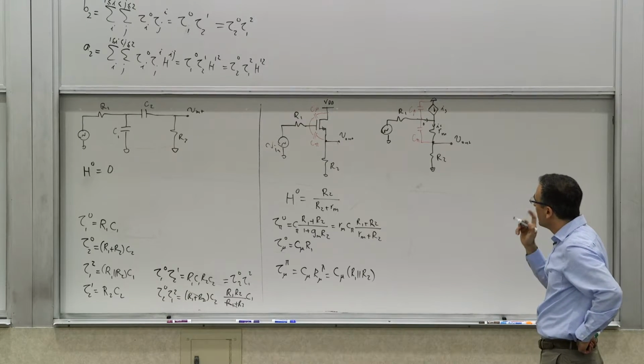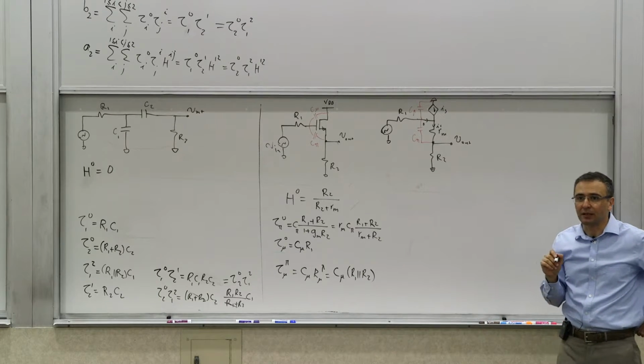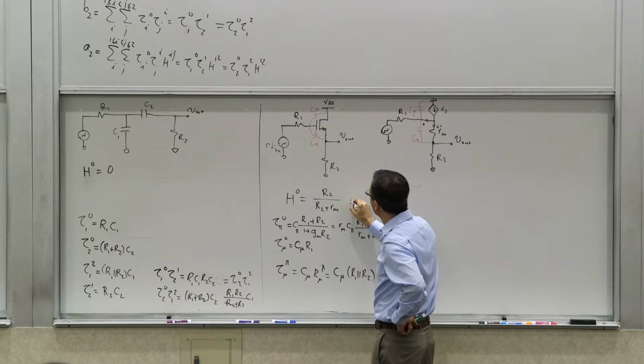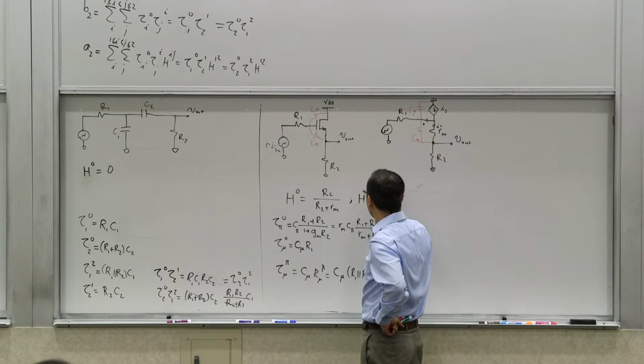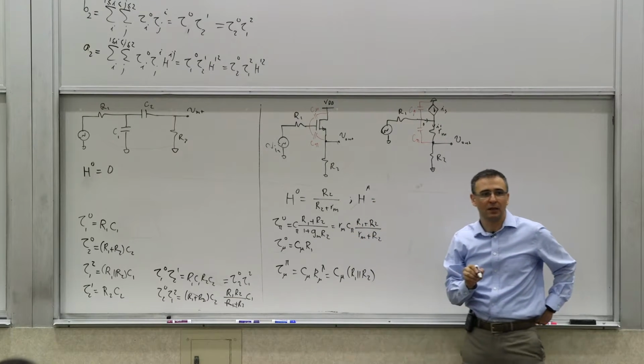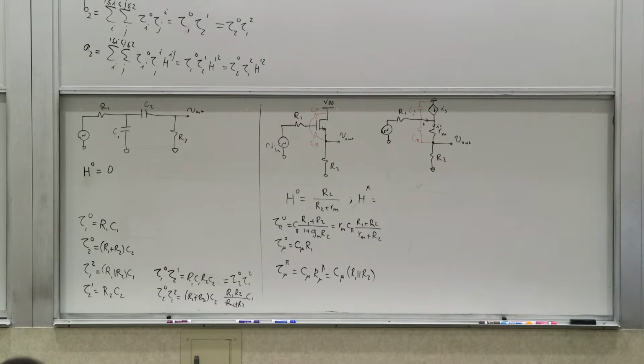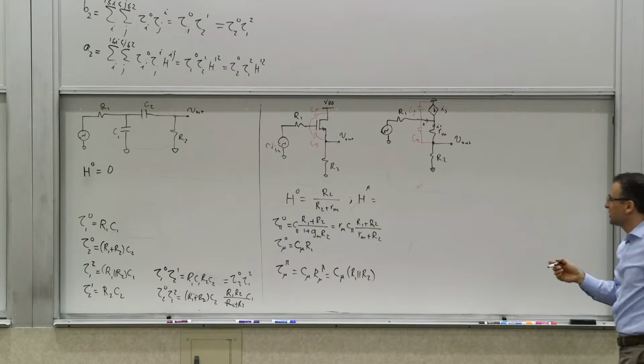we need to calculate one more thing if we want to calculate everything. So we know the h's, right? So there are a bunch of them, but let's calculate them. What is h mu? H mu is the transfer constant when C mu is infinite value, shorted. What happens if you short circuit that C mu? Nothing gets to the output, right? So this is going to be 0.